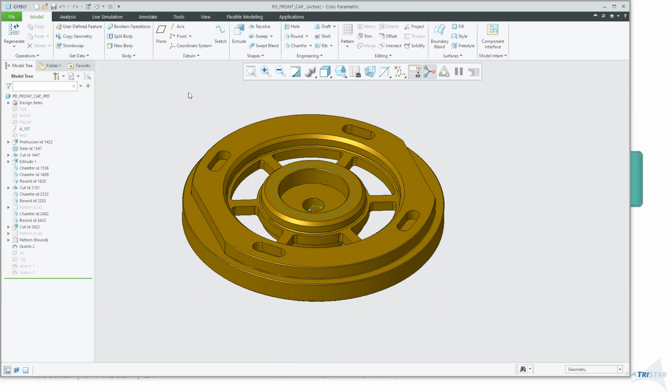Where we would have to really create UDFs is a workaround. I'm sure most of you are using it right now. It's still not a perfect or an efficient way. I understand some of you may be using UDFs whenever there are some holes in the PTC software on such types of features. What I've done in the past, like I showed you for that tapered and straight, I would create a UDF with several options as a tabled UDF where the user would use that. It requires a little bit of setup, obviously, but right now it'd be nice to have that out of the box from PTC. It's a good point.